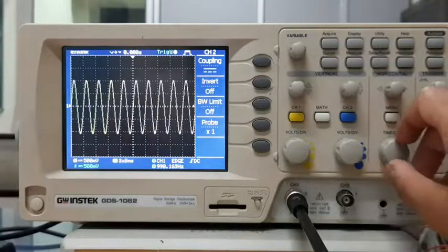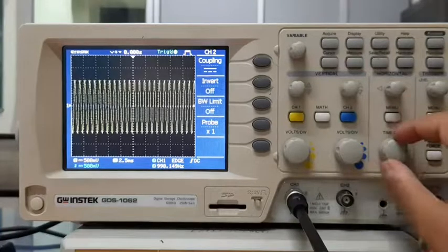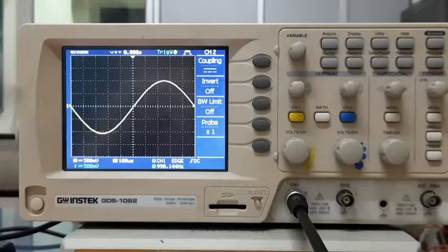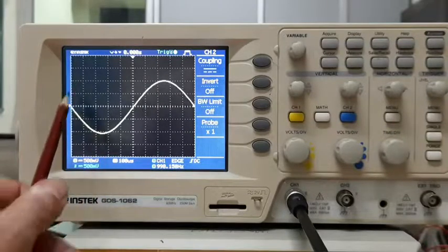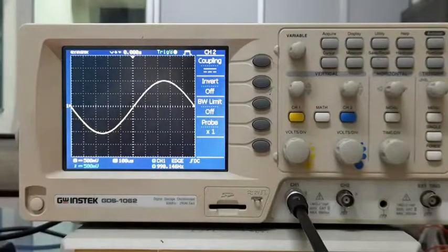I can go higher and higher, and if you are not in the proper range again, then basically you will see many more cycles than you can get information from, right? Or you can lower the range. So for example, here now I'm at 100 microsecond, so the total will be about 1 millisecond, and that's exactly fitting with one time period or one full cycle of my waveform. So I can see it like one full waveform, right?